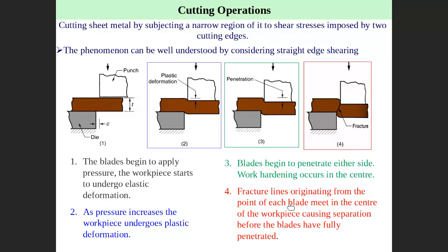And this is sheet metal cutting, 16.1. Cutting is actually preparing or cutting the sheet to the required size. I mean, the word cutting means to cut the sheet to the required size for another sheet metal process. The cutting here is shearing. So shearing means we have, as we discussed last time, punch and die. This is a tool for cutting, and this is a sheet.